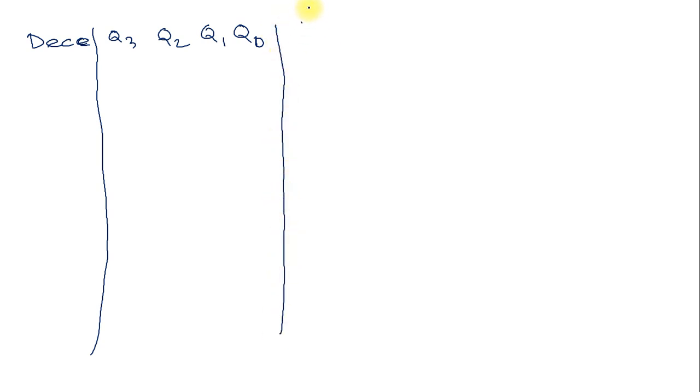As I told you in the last mod 6 counter design, we need a clear or preset asynchronous input to direct the counter to terminate its counting sequence at a specific pre-provided state. Generally the two asynchronous inputs are preset and clear. Here also we are using the clear input to initialize the counter, so I am calling it CR, the clear.